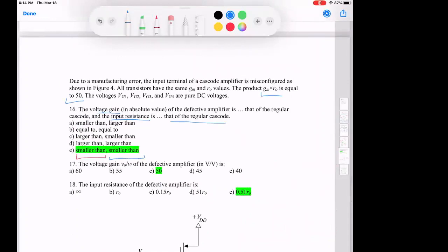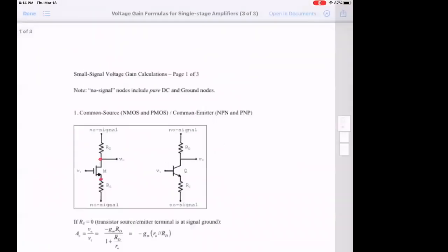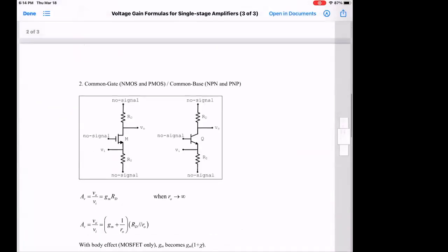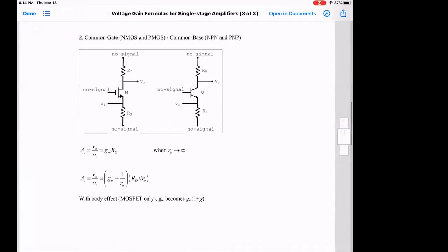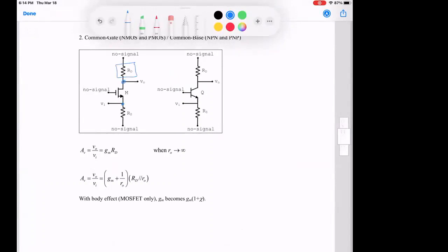Now he asks me to find the gain of this amplifier. I go straight to the circuit for the gain of the common gate, which is here. Looking at it, it says that if you have the input at this node and the output at this node, find all the effective resistance beyond the output node outside my transistor if I make a circuit of it. And also find outside the transistor at the source all RS.